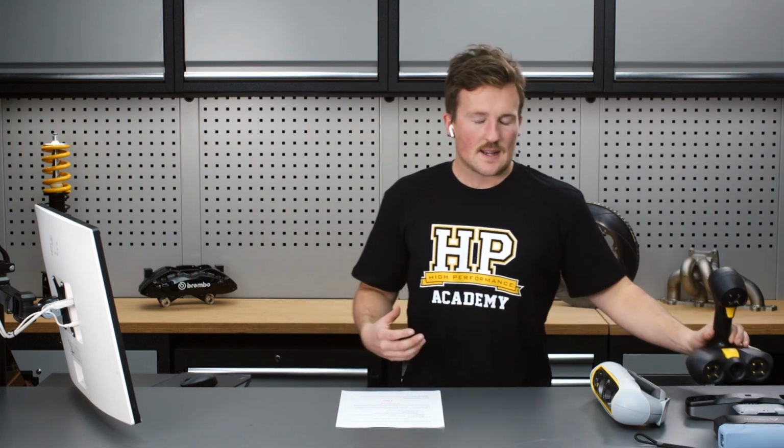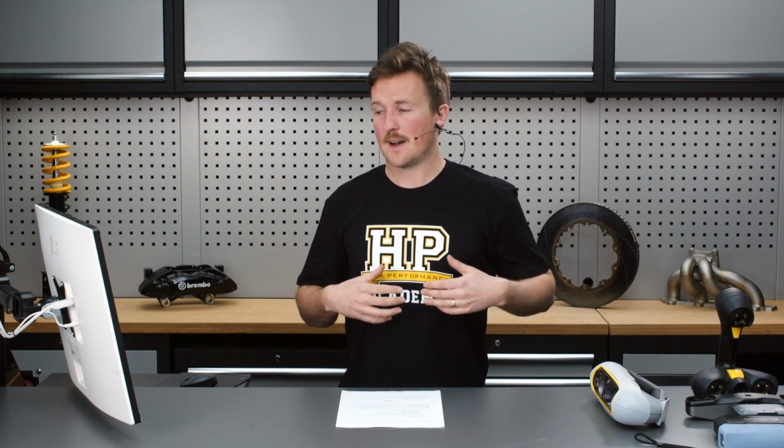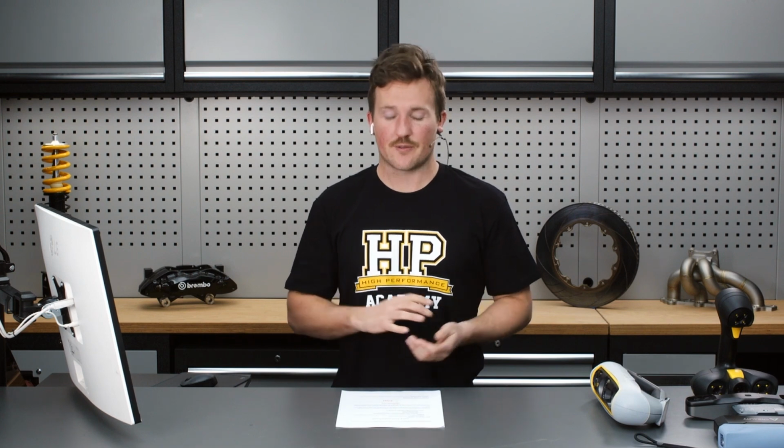So it just depends what you're going to be working on. If you're scanning small parts, high resolution, with a lot of detail, then good resolution is going to be important to you. If you're just scanning the exterior of vehicles, maybe you're always designing body kits or aero packages, then having a bigger working distance or field of view is going to be more beneficial to you.